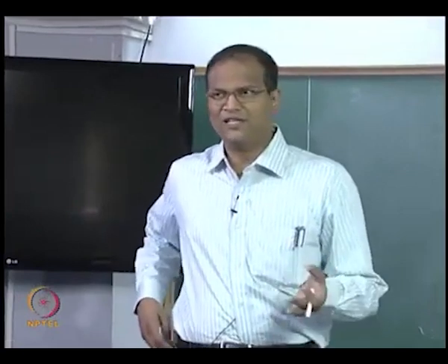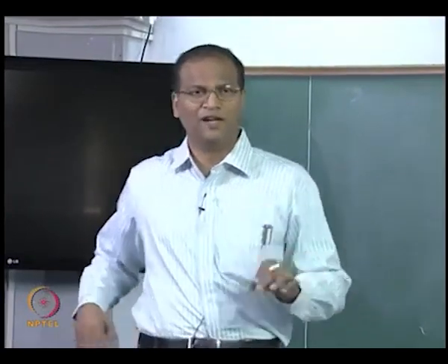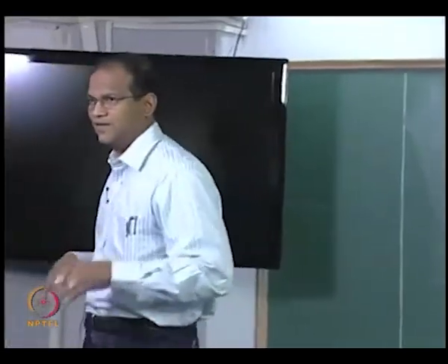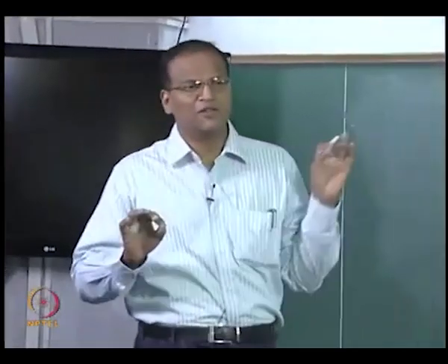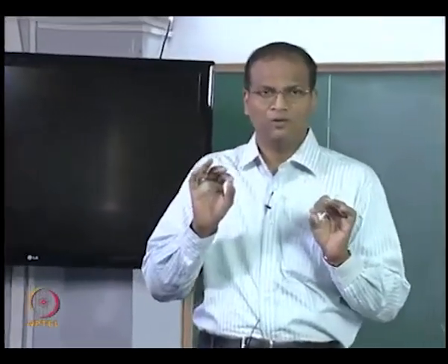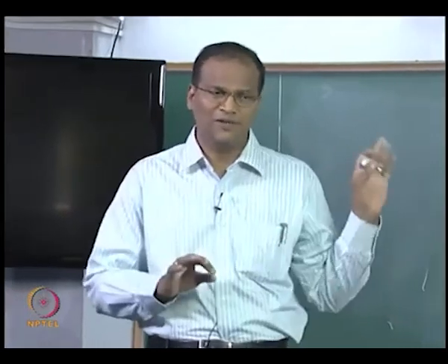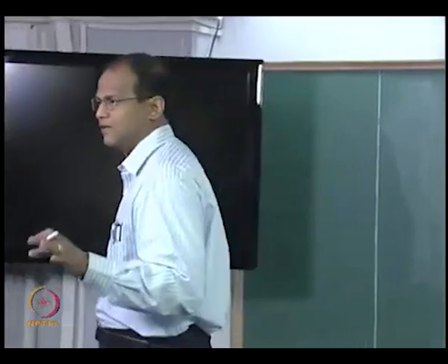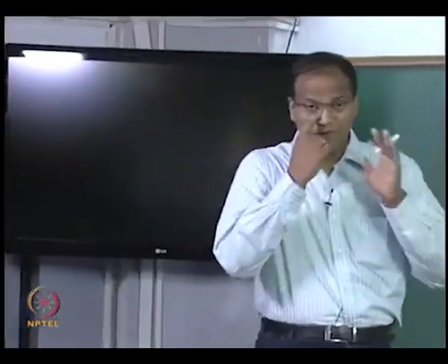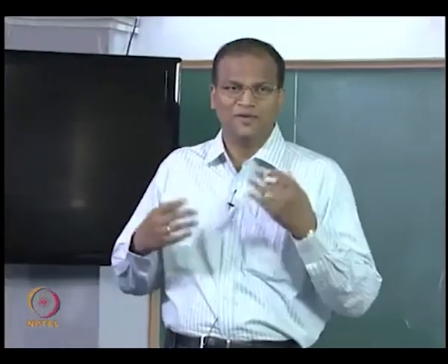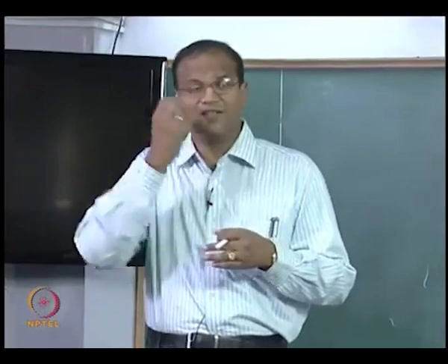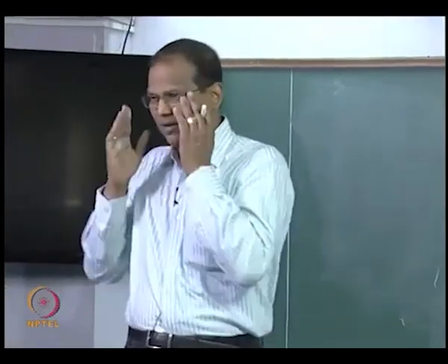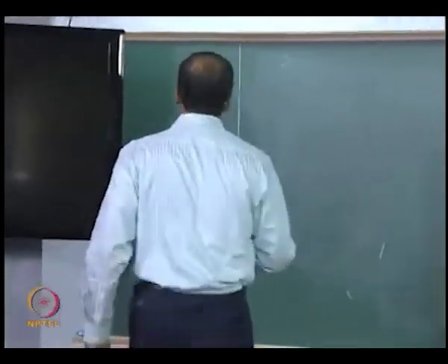If somebody says what is the energy equation, I forgot, what are you, give me half an hour I can derive it. Just draw a control volume, find out what are the flux, do a flux balance, and then the key information which you are putting is only one, qx equal to minus k dou t by dou x, otherwise everything is only thermodynamics knowledge. Then your knowledge of vector calculus and all that, that is it. Then you should be able to recreate our knowledge with just basically a few things, from that you should be able to build, okay. So now if the body is stationary,